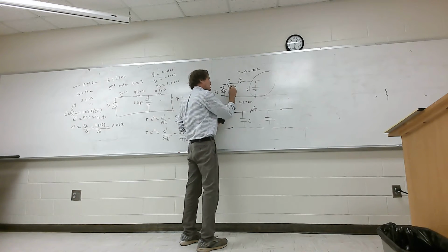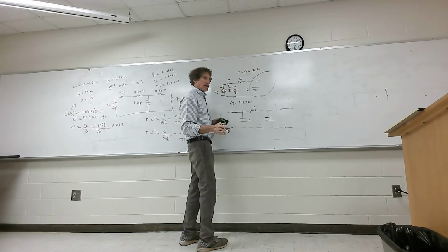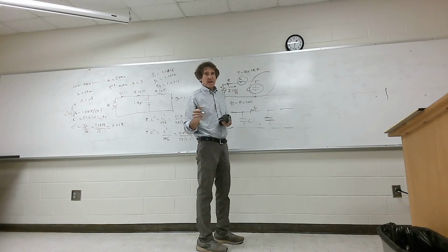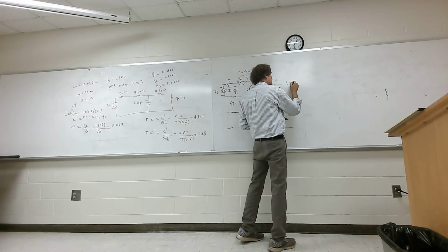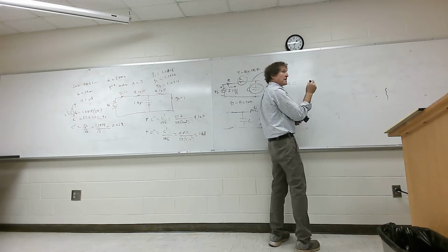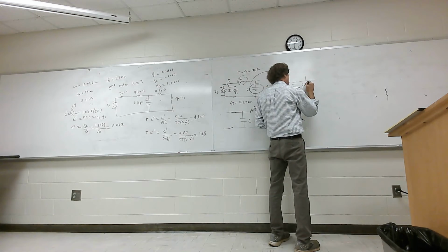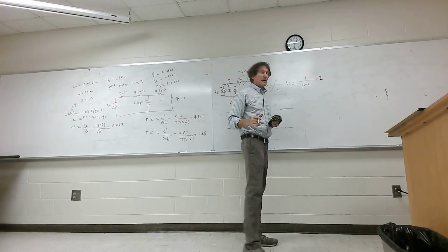So you're going to get a current here, I, that's just Vs divided by R. That will be the current, right? But what's going to be the value of the capacitor and inductor voltage? Well, the voltage on this capacitor is the impedance of the capacitor, which is 1 over j omega C, times the value of I, right?